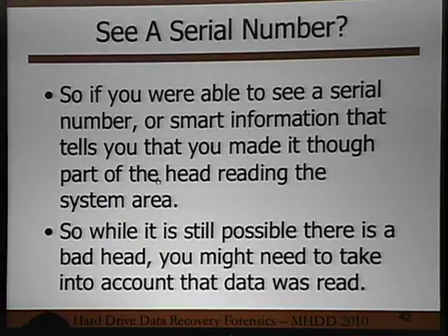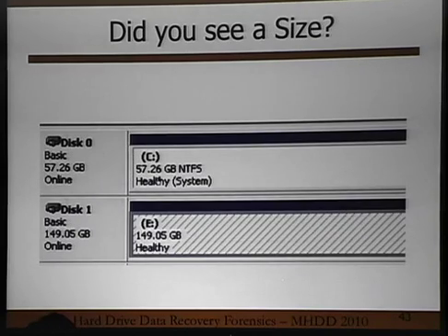So again, pay attention to serial numbers, model numbers. If you get even this far, where you mount a hard drive in Windows, and you don't get something like NTFS, but you get a partition structure in a drive, well, I probably made it through the system area, probably made it through the initialization. And if I'm getting a partition and the size actually looks like the size of the drive based on the sectors written on the lid, I'm probably in pretty good shape.